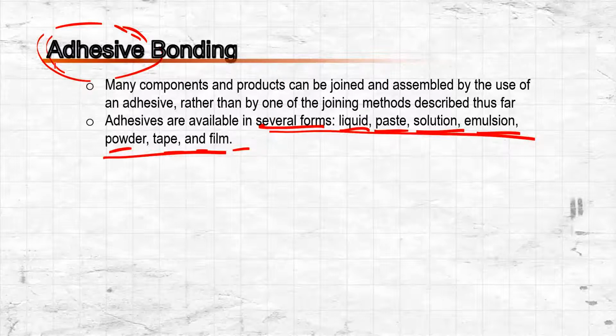However, the downside of this adhesive material is the temperature. If the temperature is beyond the capability of the adhesive, then the joint will fail, whereas metals can withstand higher temperatures. And of course there are going to be proper applications for adhesives. Should it be in shear, or should it be in tension, or things like that? We have to consider that as well in applying the bonds.